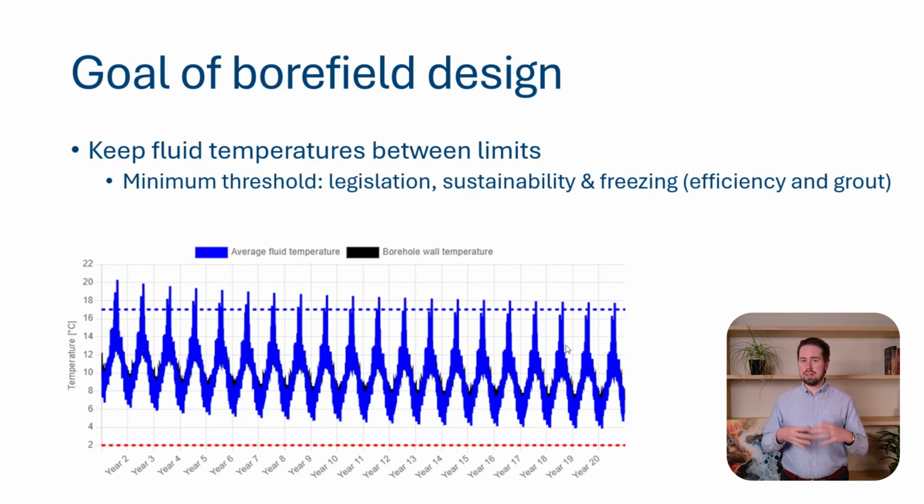Typically, it's 0 degrees as an average fluid temperature in your ground, or perhaps it's 0 degrees going into your ground inlet temperature. If you're, for example, working with water, there is a risk for freezing, so you want to stay above this 4 or 5 degrees inlet fluid temperature. So perhaps there is a standard for it.